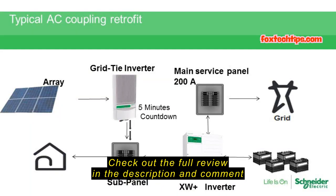With a typical AC coupling retrofit, we see the grid tie inverter there, and probably the most important thing to note on this system is that the sub panel is being shared by the XW Plus inverter as well as the grid tie inverter. So during normal operation, when we're selling power out to the grid, the XW is literally just a piece of wire. It's in a pass-through mode, so the grid tie inverter is simply passing through onto the main panel and then out to the grid in this example.